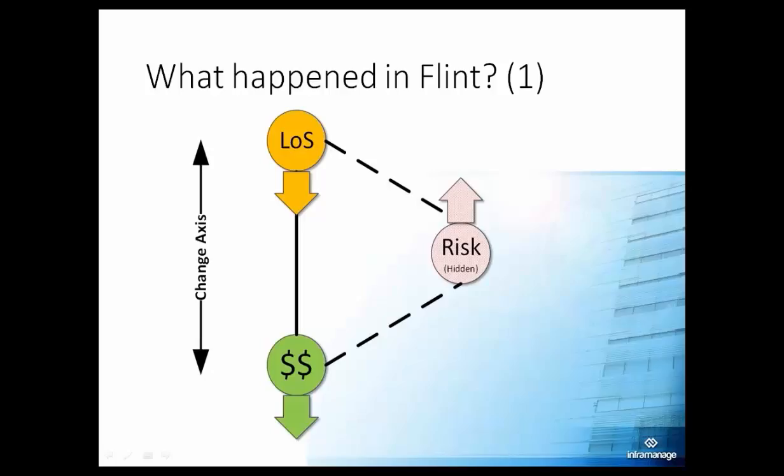The other thing to look at is, is it just a pipe that's feeding half a dozen houses, or is it the main pipe in from my tank and my well field? So what happens if I lose that pipe? That might cause you to look at condition a little bit differently. But age approximation is where you start, and working out the ones that are in the last third of their life is a good rule of thumb to guide any further work that you might want to do.